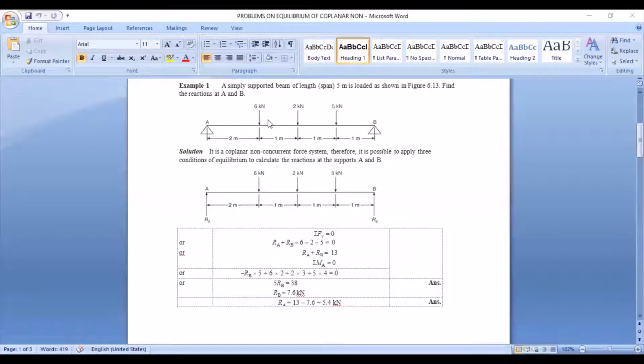When we look at the loads, I've told you that the loads should either be vertical or horizontal. If not, you're supposed to convert them to horizontal and vertical loads. But in this specific problem, we have only vertical loads and we are going to show them in their position only, as shown in the free body diagram. So actions are being displayed.